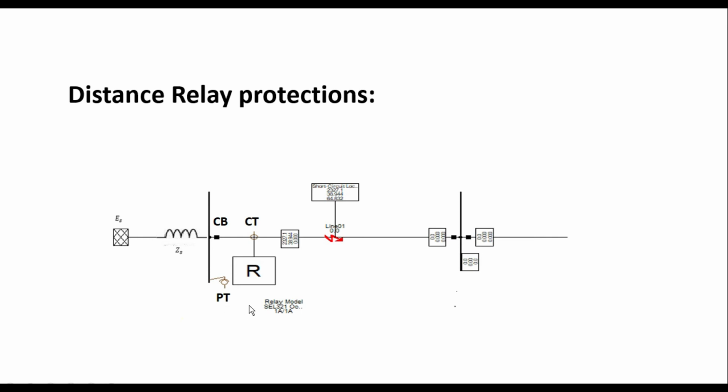There is the relay setting impedance Z, known as the replica impedance, which is an equivalent impedance of the line, multiplied by the CT and PT ratios. Then an equivalent impedance connected inside the relay will be obtained. So the values of the replica impedance, currents and voltage are used to provide the exact location of the fault point.